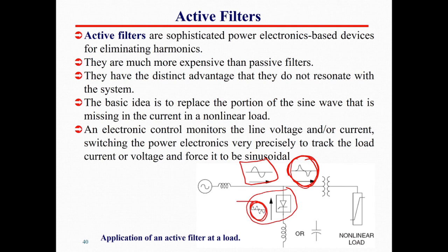That means if we add those two components, the sum will be equal to the current taken from the source. As a result, anything connected over here will not be affected by the nonlinear load. Okay, so that means, for example, if we have any load connected over here at a certain bus, it will not see the nonlinear current that is flowing through the nonlinear load.